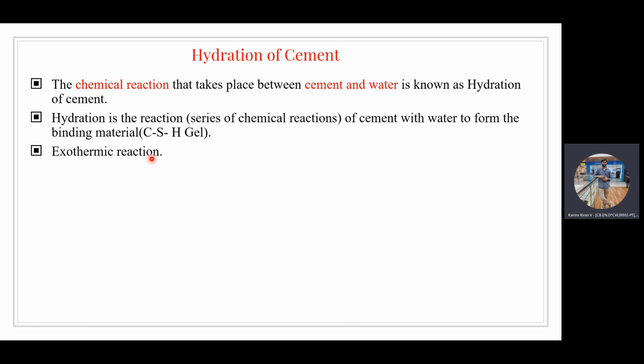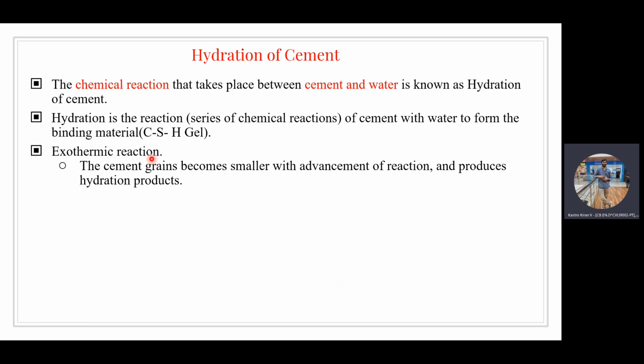Whatever hydration reactions we are having, all those reactions liberate a certain amount of heat, and such reactions are called exothermic reactions. In the process of exothermic reactions, the cement grains become smaller and smaller as the reaction goes to deeper levels.